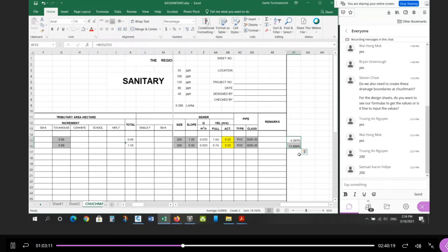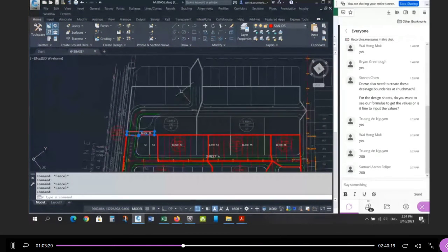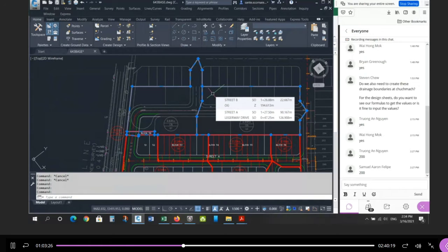Okay? And I'm going to say something that's a little crude. I'm going to apologize in advance. That additional area, this little piece here, contributing to these 2 areas here and here, is so insignificant. And the phrase I use, and it's a bit crude, I apologize, it's like peeing in the ocean. It has little to no effect. Yes, you have to account for it, but on a practical level, it does nothing to the actual flows you're expecting on a practical level. Therefore, these pipes that are already in the ground can take that additional area. It's not that big a deal.